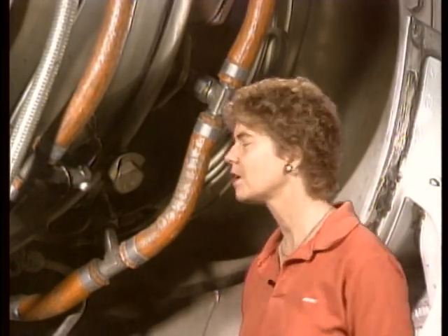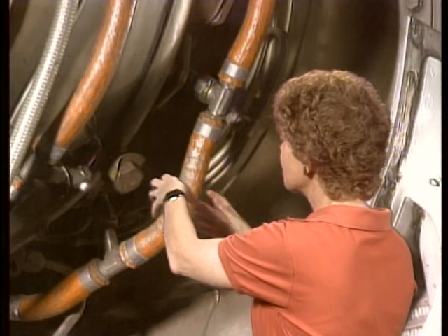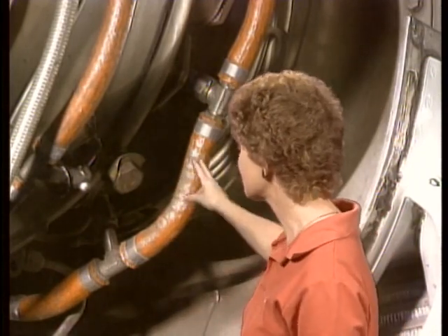Now, as I said, you must have a certain amount of slack in flexible hose when you're installing it, and the reason for that is when it's under pressure, it's going to do two things. It's going to contract in length, and it's also going to expand in diameter when it gets under pressure, and that's why it needs the slack in order to be able to contract in length. Okay, how much slack does it have to have? Flexible lines have to have 5 to 8% slack.